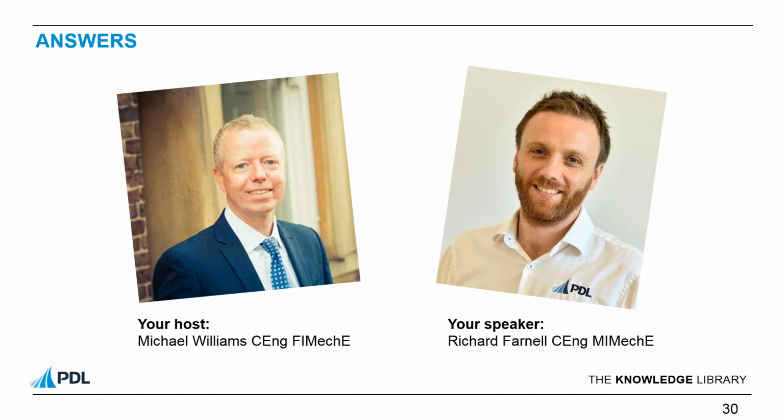Actually, one of our BVAA Future Leaders program colleagues raised this one amongst a couple of others, and it was to do with the material curves. Are these actually coming from testing, or are they from calculation or code? Okay, so the material curves, you can use actual material curves if you have them. So if you've done some testing and you've developed true material behaviour for your particular material, then you're welcome to use that.